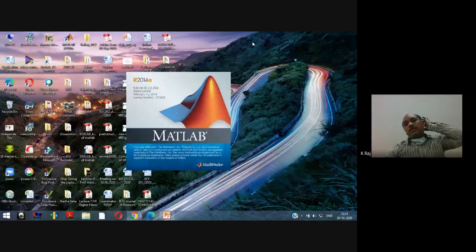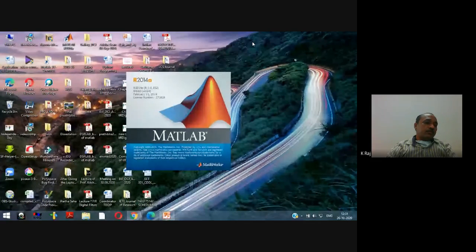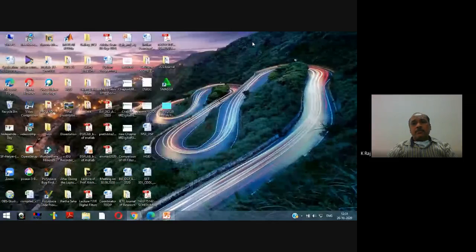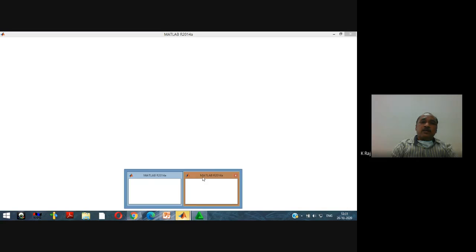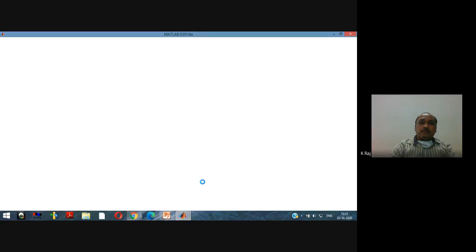And the third step is using the block diagram concept here. That is, whatever the design is, the realization will be described. First of all we have to derive the mathematical model, in the time domain or in the transform domain. Then we can draw the realization architecture, and with the help of that block diagram we can design the filter using the MATLAB facility named Simulink, and when we save the file, it is named as the .mdl file.